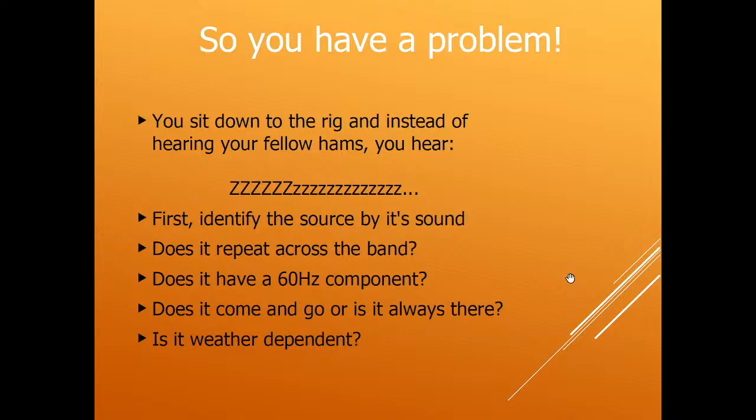And by that I mean, do you hear a similar noise every evenly spaced distance across the band? Like maybe every 18 kilohertz you hear the same kind of buzzing tone. That would tend to indicate that it's probably a switching power supply, and we'll talk about why that would be. Does it have a 60 hertz component? So you can figure out if it has 60 hertz if you have a scope.